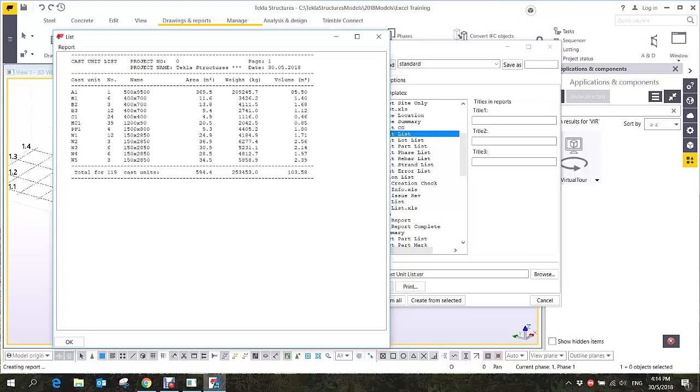You want to change the numbering? Yeah, at the moment, by default, we have this numbering system that the Tekla structure will assign the piece marking to each and every element. This one is assigned by the program itself, right? Yeah. So if let's say somehow you delete W2, will they reassign? For instance, now I got wall W1, 2, 3, 4, 5. One of the W2 is different. I delete omitted. So W2 won't be there.